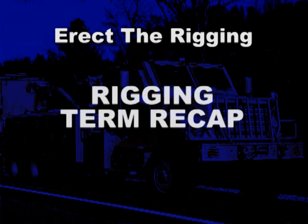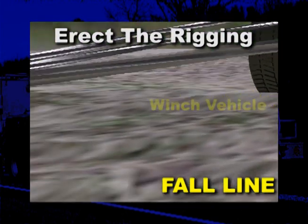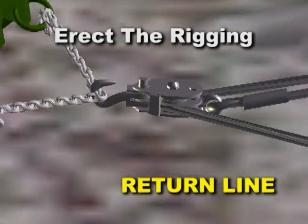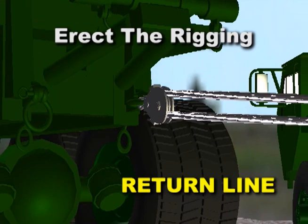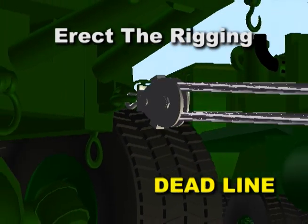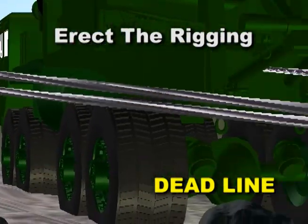Before we erect the rigging, let's recap some of the rigging terms. The fall line is the winch line that runs from the source of effort to the first block in the tackle. A return line is a winch line rigged between the blocks, or the winch line from the sheave of a block to the point where the end of the line is attached. A dead line is a line used to attach blocks or other equipment to the load or to the anchor.